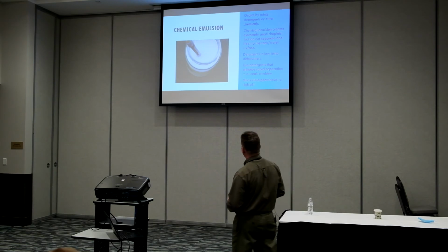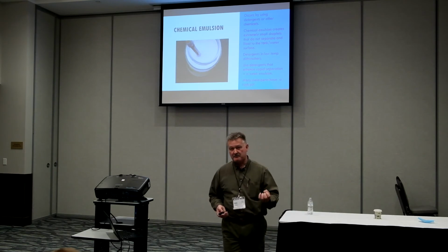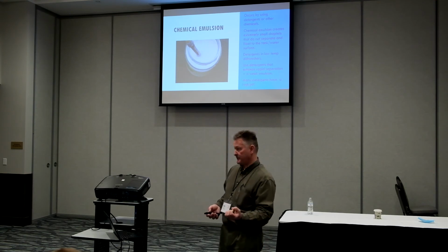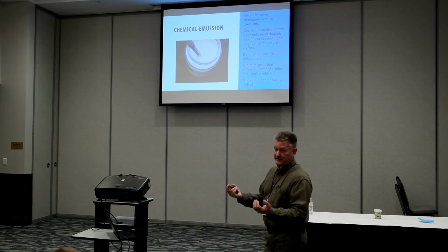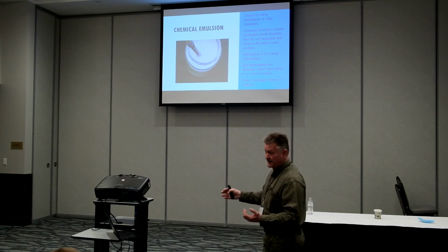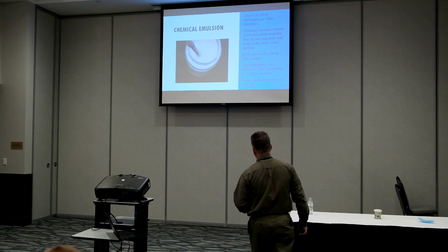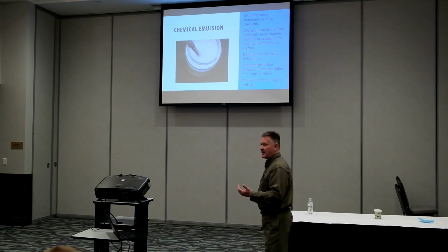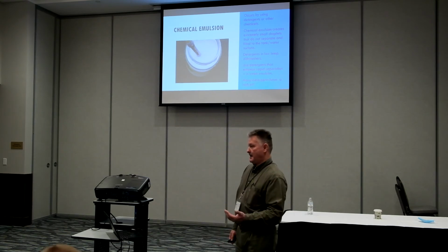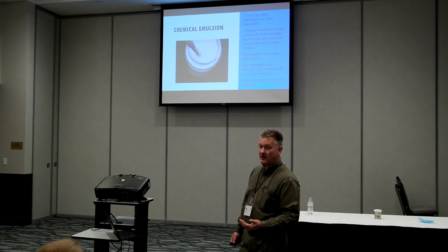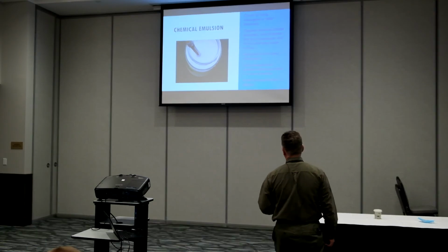So, chemical emulsification produces very minute small droplets of fat, oil, and grease, and it's very difficult for that to start separating. Oftentimes that will get carried out through the tankage into the field. One of the main culprits of that is chemicals, especially if we're using chemical low temperature dishwashers. That's going to have a tendency to produce that effect.